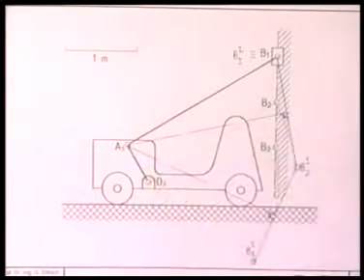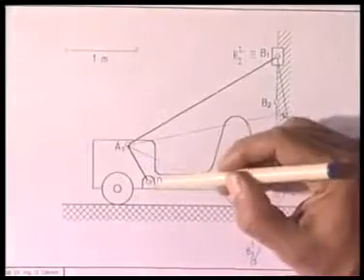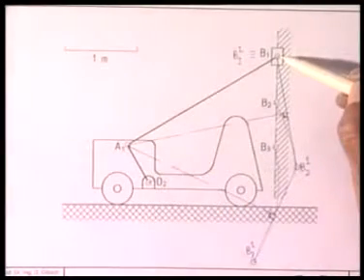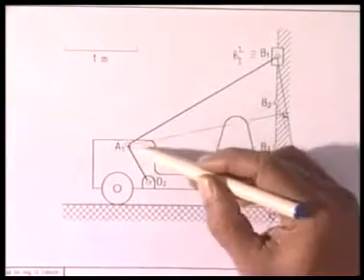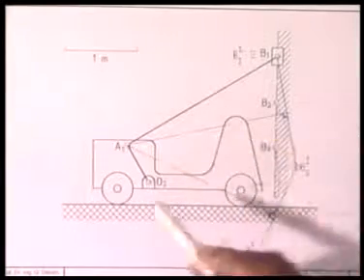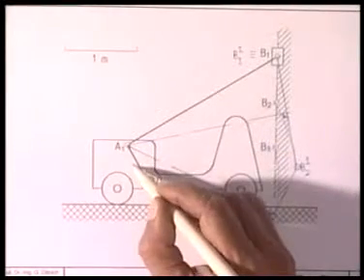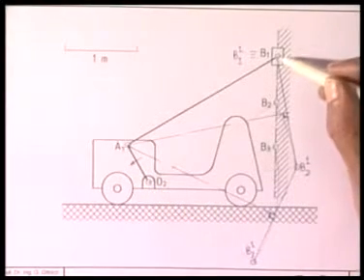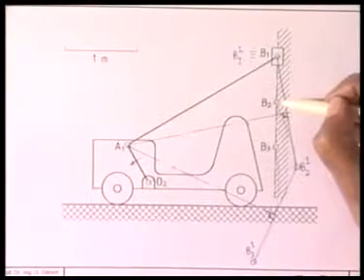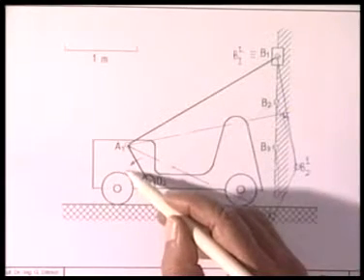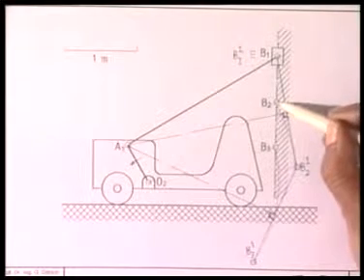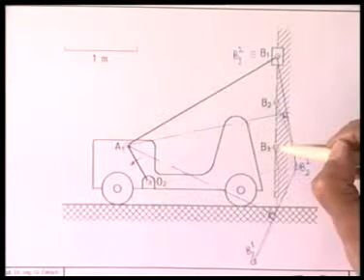at A1. So finally, at the end of the first stage, we have designed a slider crank mechanism, namely O2 A1 B1, where A1 is the crank pin, such that I know the 26 degree counterclockwise rotation of this crank will cause the slider to come from B1 to B2. Further 26 degree counterclockwise rotation of the crank will cause the slider to come from B2 to B3.